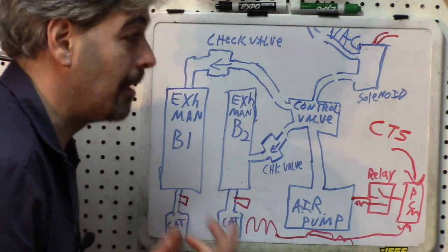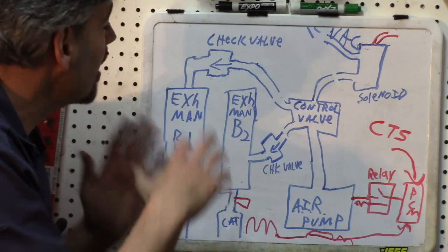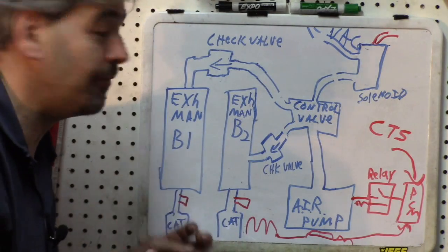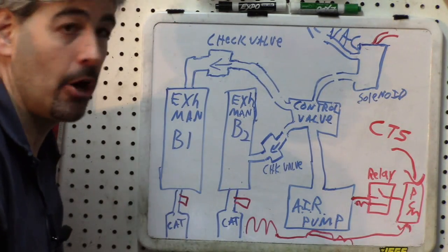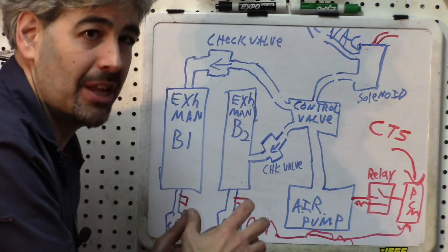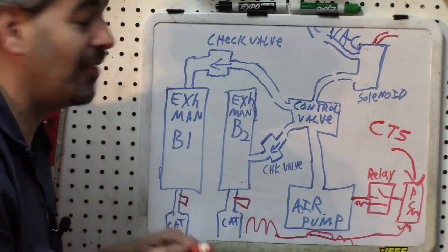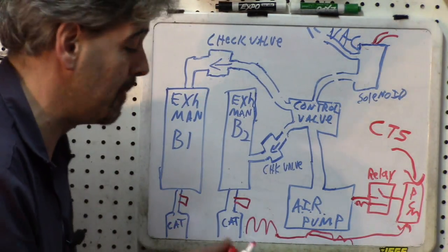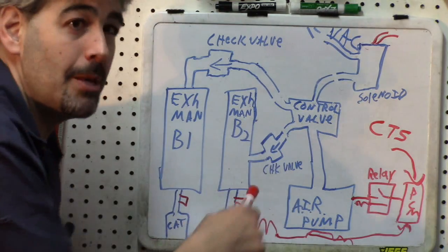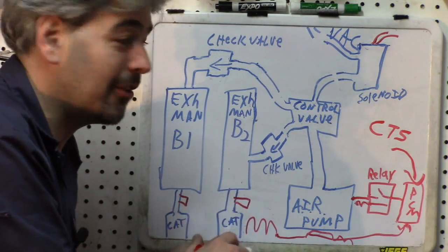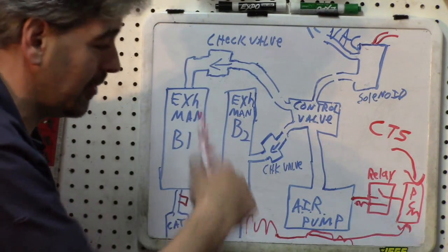And also keep in mind that on many older cars, like we're talking in the early 80s and stuff like that, I remember having a Ford F-250 with this situation. The air system has often been bypassed by owners because they had problems with the air pump system and just got rid of the system altogether. So keep that in mind. In many states, that is actually illegal and would cause a failure of emissions. I know in Missouri that was definitely the case for one truck that I worked on. So do keep in mind, because people don't understand the system, very often they just get rid of a system that causes problems if they can. So just keep that in mind.